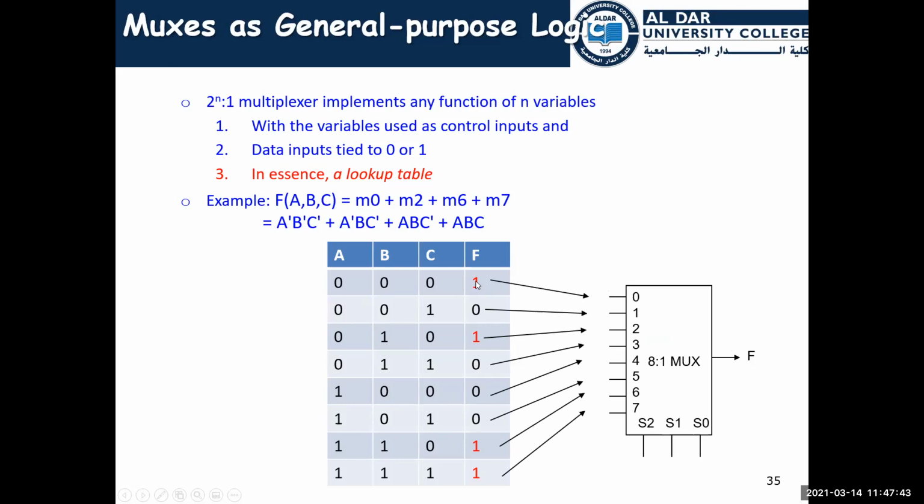And this way we will connect this one to this terminal. We will connect it to 1, and this terminal will be connected to 2, and 0 will be connected to, and so on. We just connect, 0 means ground, and 1 means connected to the voltage source. So it is very simple. We connect I1 to ground and I0 to voltage source or high voltage.